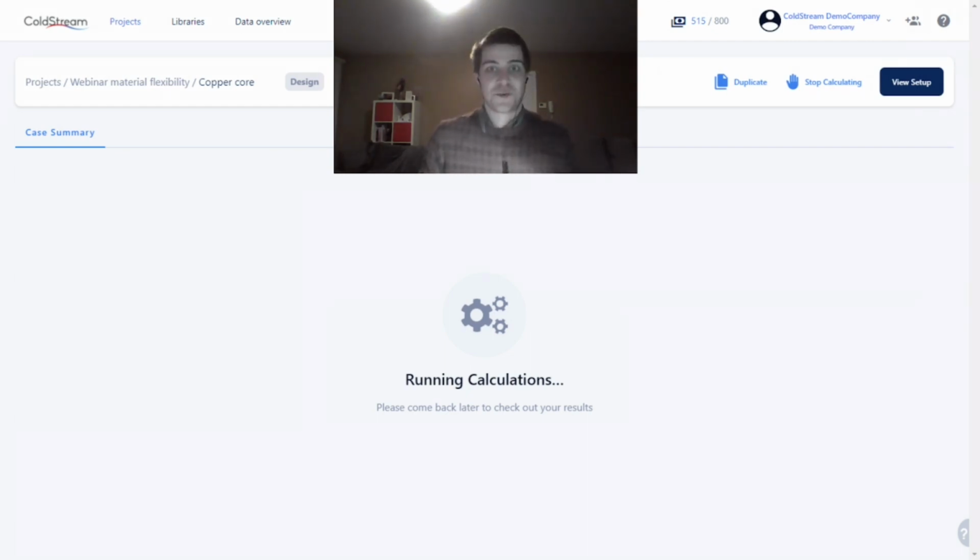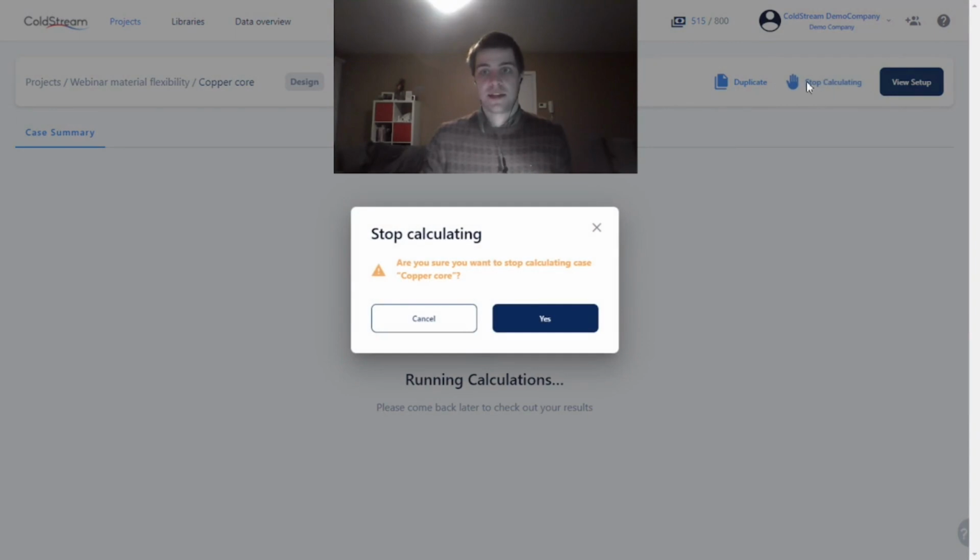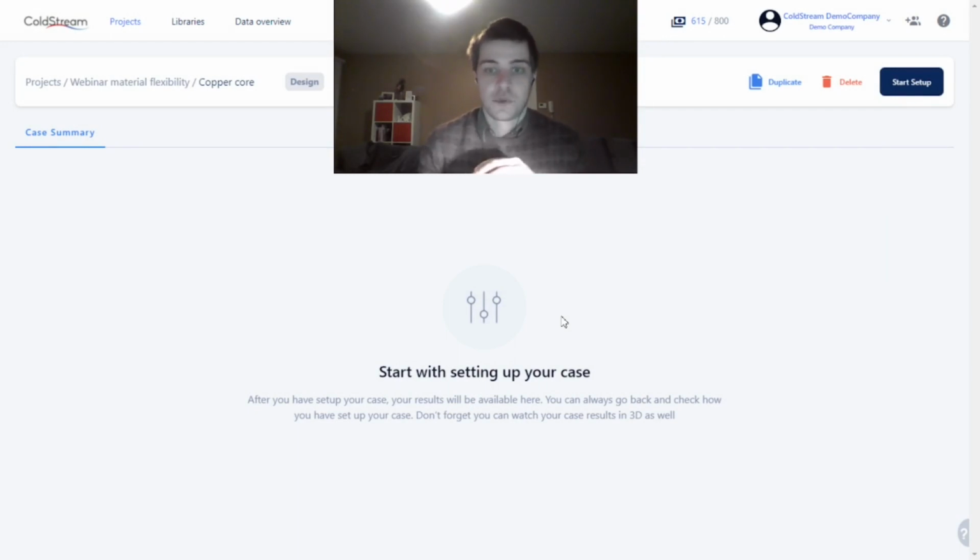Of course, we don't want to wait for 8 days and 14 hours, if I remember correctly. So that's why I prepared for this webinar, so I can stop the optimization process by clicking the stop calculate button and confirming that I want to stop this case. When you do that, all of the progress, all of the data is deleted. So if you, for instance, stop your case and resubmit it, hoping that it will pick up from where you left off, that will not happen. Really all of the data, all of the progress is deleted. So be careful when you click that button. Don't make the decision lightly.